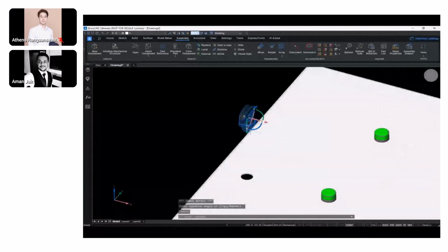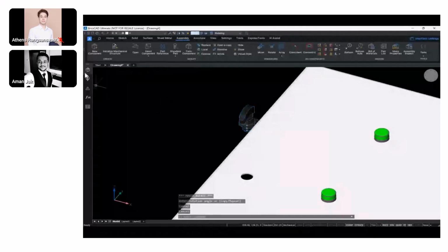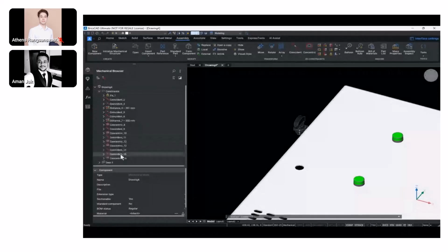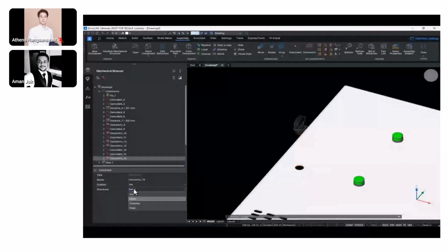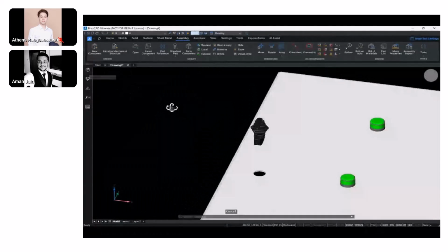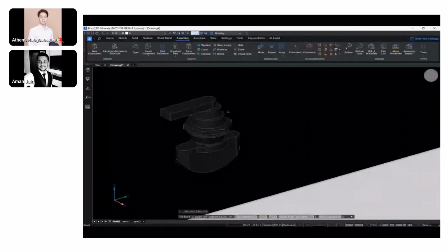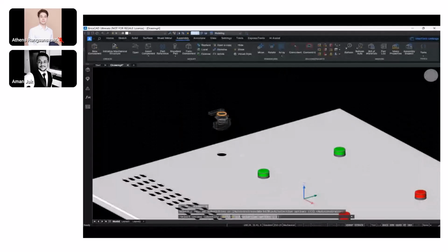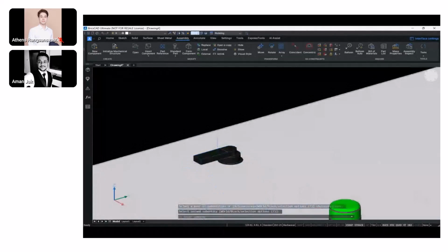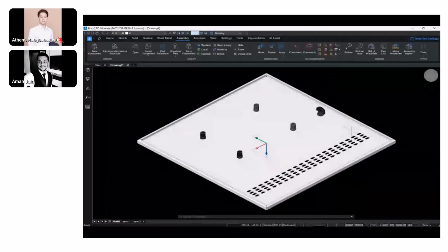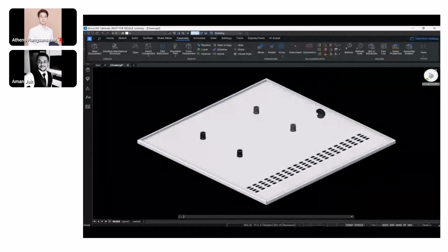Oh no. Since I've constrained it, I'll not be able to rotate it. But what I can do is, for the concentric constraint that I've applied, in case I want to change the directions, right now they are the same. I can simply set it to opposite and it just inverts itself. So instead of rotating it manually, since I already applied the constraints, and rather than deleting it, I can simply change the directions in which the constraints have been applied, right? So this helps me create the door lock, and that completes my entire assembly of the door, right?